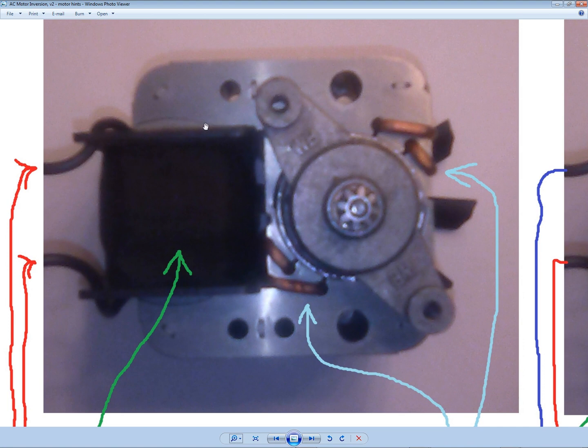And then there's a bobbin here, a plastic bobbin, that goes, again, through a slot down here, goes through all the laminates, comes back the opposite side, and comes back over to here. And then what we're looking at here is tape, a cloth tape that surrounds the windings. And I peered into the edge here, and I found that it was very thin enameled magnetic wire. I'm assuming it's enameled magnetic wire. But very...